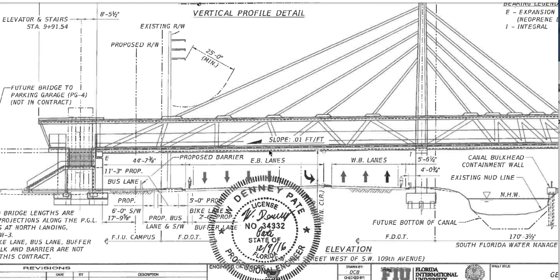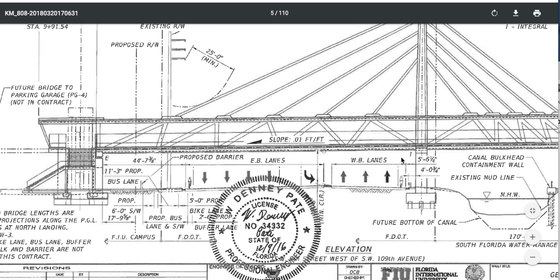And the engineer said, don't worry about it, that's okay. It's post-tensioning. This is not rebar that has to become active. With rebar, you get a little deflection and the rebar becomes active. This is post-tensioning. It's active from the start. So with any deflection in this deck, your post-tensioning is getting even more loaded by the dead loads. So when they removed the scaffolding, it deflected down. By doing so, it acted like a tied arch bridge at that point.